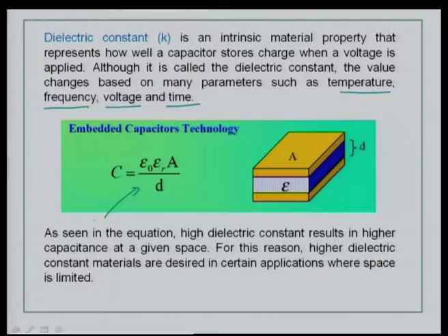So, if you want to use, for example, a sequential build up technology and employ different embedded capacitors in the build up, one above the core and one below the core, you can very judiciously use different capacitor materials to get different ranges of values, one at the top and one at the bottom, interconnected. These capacitors can be interconnected to the signal layers, the ground planes, and to the core by microvias.